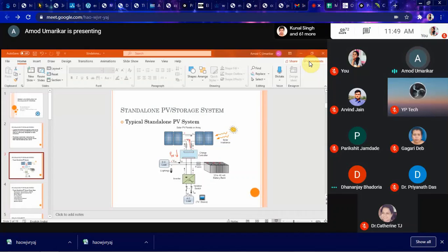Then the next part is battery selection. We have to select the proper battery based on the first and second steps. Based on the first and second, the third step comes, which is PV array sizing. PV array sizing is the main thing, where most of our job is done. Module and charge controller are obvious steps. We will mainly focus on the first three steps.